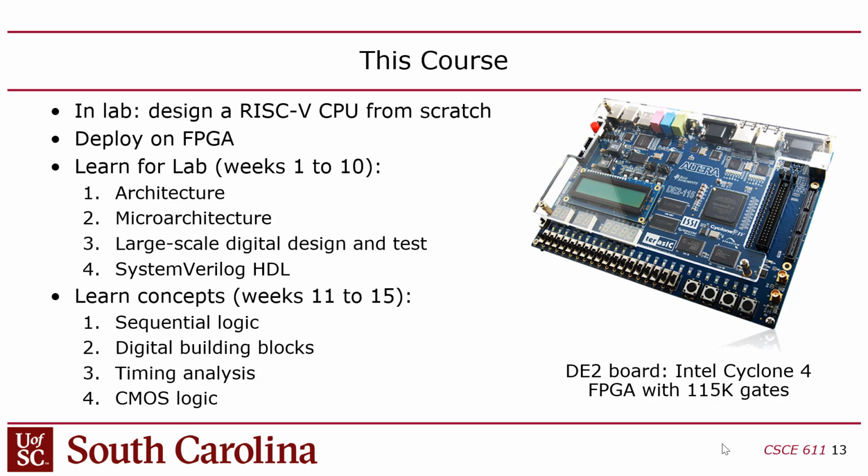But the design process is very similar. ASICs are also designed with HDL, right? The only difference is in the tools. With an FPGA, you take the HDL code and compile it down into a bit stream for the FPGA, whereas with an ASIC, you compile it down into mask shapes, polygons that you send off to a fab over in Taiwan, and they'll use their piranha acid and sulfuric acid and horrible, deadly, nasty chemicals to make it, right?